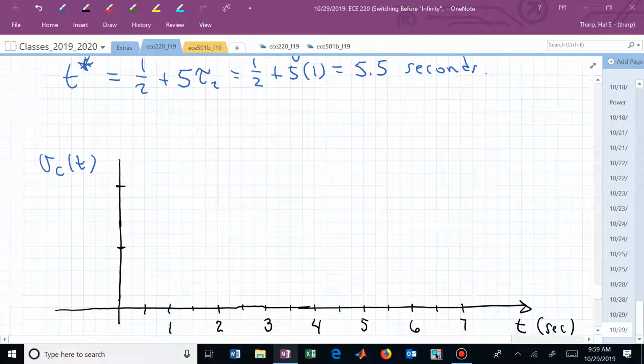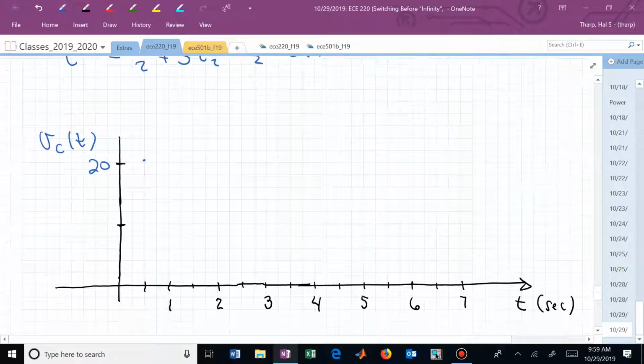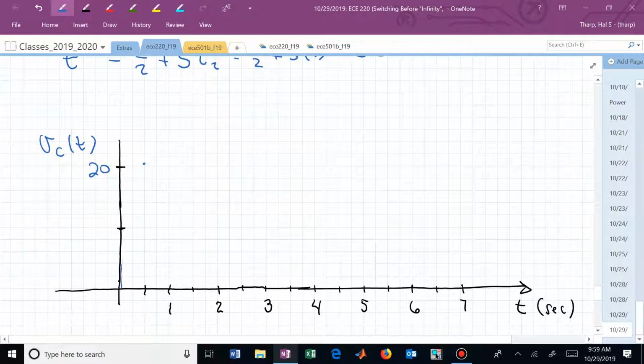And if we now tried to sketch that, let's say this is now 20. We were up a little above 20 at 1/2. So now we were doing an exponential up to there. And then beyond that, we started exponentially decreasing. So in one time constant, which our time constant now after 1/2 is 1, at 1.5 we'll be at e to the minus 1 from 20.